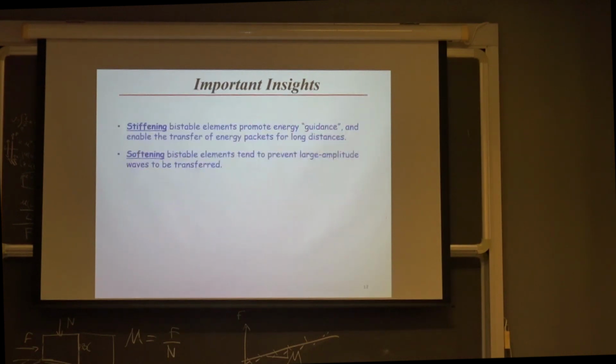Okay, so the important insight that we learned from the 1D response is that stiffening bistable elements promote energy guidance and enable the transfer of energy over a long distance. On the other hand, softening bistable elements tend to prevent energy from penetrating deeper into the lattice.